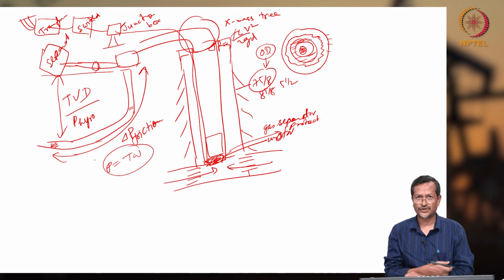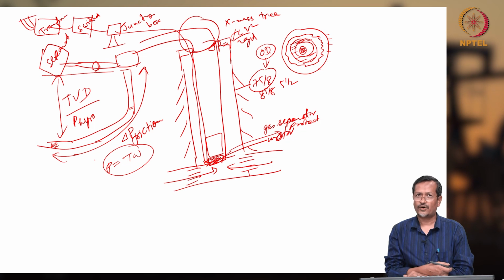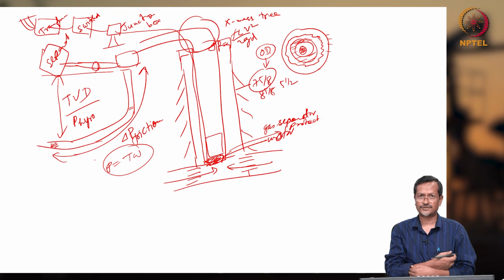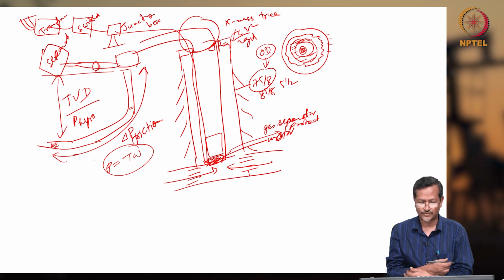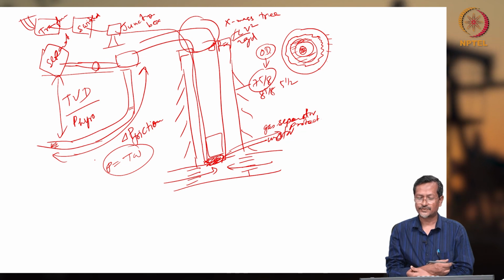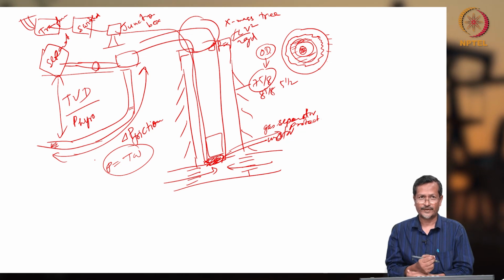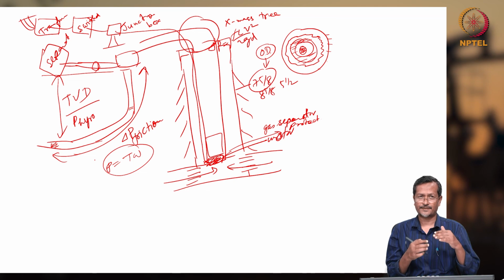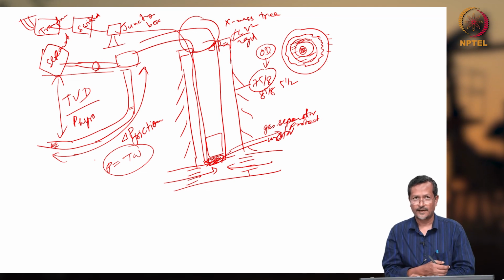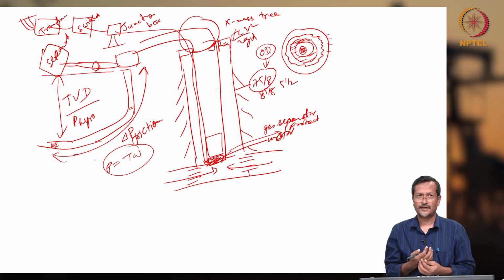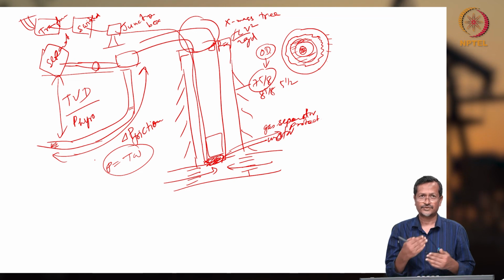Okay, now if you want to calculate friction or pressure drop, then there are several charts available, or you can use some approximate formula. And hydrostatic pressure you can calculate using correlations again; multi-phase correlations are there, single-phase correlations are there, which you can use for single-phase fluid flow. Single-phase fluid flow may have different viscosity, oil-water viscosity, or an emulsion can be created, or if it has gas bubbles, again there will be another issue, multi-phase flow will be created, whether you are creating a separated model or a homogeneous model. You can use several software packages available these days, but still you have to know how things are happening. So some manual calculation you have to do.